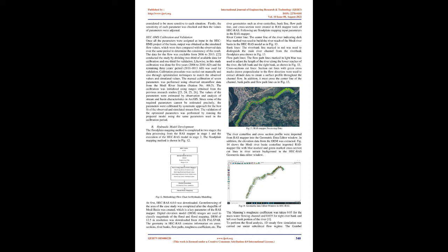Developing HEC-HMS model files. In this step, model files such as background map file, basin model file, and meteorological model file required for HEC-HMS were generated. Finally, the background map file and basin file were created to export to HMS. In this case, simple canopy and simple surface methods were used. A canopy component was included to represent interception and evapotranspiration. Similarly, a surface component was added to represent water captured in surface depression reservoir.